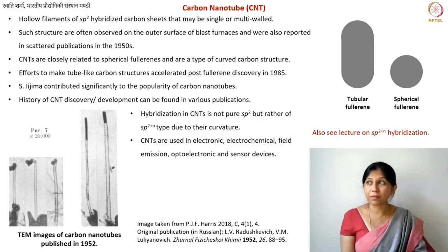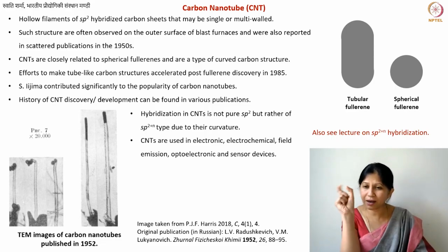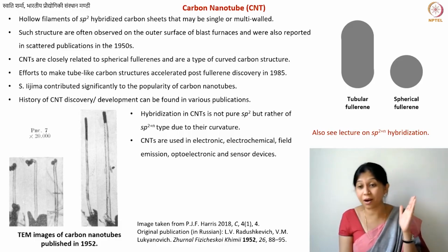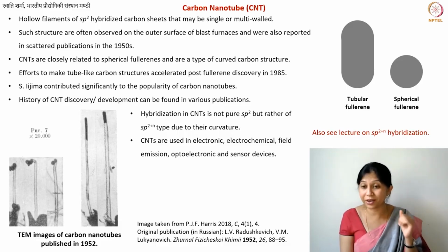Carbon fibers, why do they have cracks? Whenever we were talking about the weaker links in your carbon fibers, why do you have weak links and weak points? Because these are the points where you have voids of some kind, or because you were deriving the carbon fibers from polymers by heat treatment of polymers.